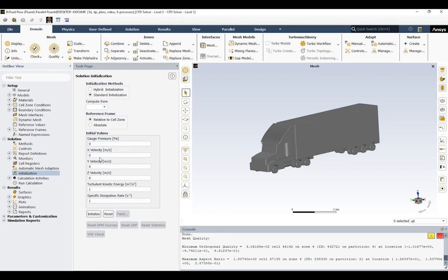It should be mentioned that based on the values that you define here, your simulation may converge sooner, but that doesn't make that much difference. A better way to have a better initial guess is to select, for example, a boundary from the different boundaries in your model.